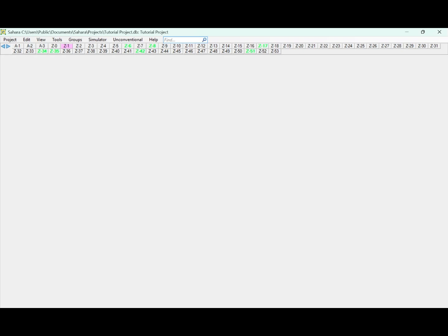The flow element, as we discussed, is where all these equations will be applied, and we will need to characterize it by its pore volume. The minimum data is always the pore volume, the initial and residual oil saturation, and the petrophysical parameters that will be required by the calculation model that we use. This last point will obviously change from one model to another. For example, in the characteristic curve, we will not need as much data associated to the wells as with the other models that will use more information, for example the Corey exponents that will be used for Buckley and Leverett.